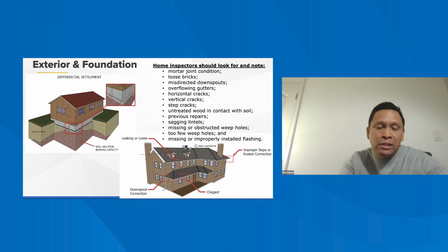So when we're inspecting a resale where the basement's completely finished, how are we going to know if that crack is transitioning all the way through the wall? The only thing that we can do is just inform the client and say, just so you are aware, I can't see the other side, so just keep an eye out. The carpet's not wet today. The bottom part of the drywall is not wet today. The wall is not showing moisture stains. My thermal imaging camera is not showing any anomalies here. My moisture meter is not picking up a high moisture retention reading.